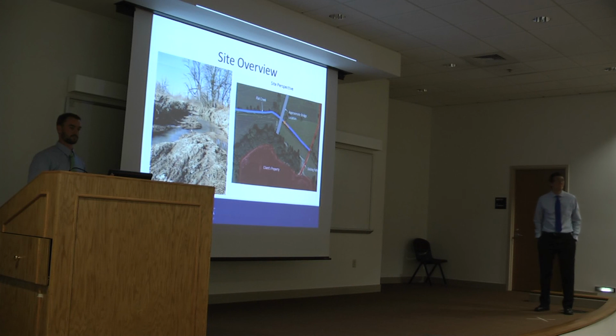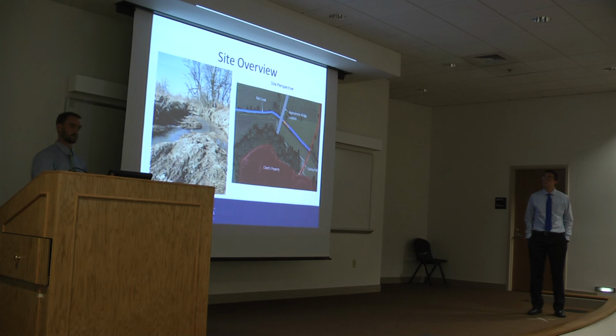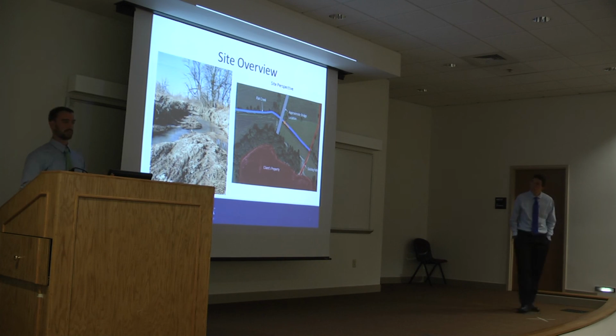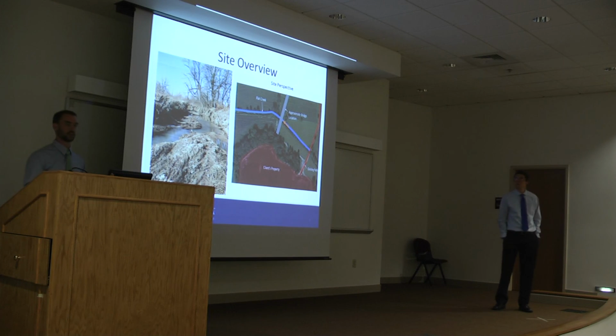Other questions? When you were building the model of the creek, you did a 100-foot resolution. Is that a standard resolution for creating a model, or should you have gone smaller or larger? No, that is the standard. If you wanted more detail, you could cut it up into smaller chunks. If you wanted less detail, you could do larger chunks. Based on 100 feet, it would give us roughly 10 to 11 cross sections, which we felt would give us a good idea of what the creek bed itself would look like.